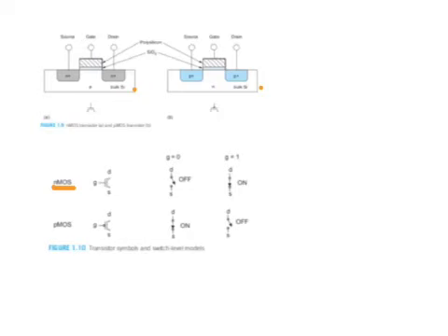The device has three terminals: the source, the drain, and the gate. The source and the drain are in an unactivated state. The source and the drain are not connected. That is, free electrons in the N plus wells of the source and the drain cannot flow between each other. By applying a positive voltage on the gate, minority electron carriers from the P region migrate to form, electrostatically, a channel bridging the source and the drain, which then allows current to flow.